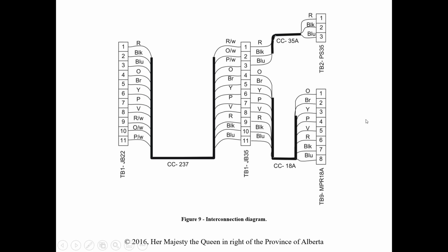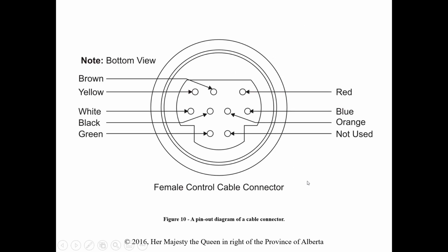Last one they talk about is the interconnection diagram. They show specific connection details, so no attempt is made to provide an indication of the function or location of components. It's literally, red goes to 8, or black goes to terminal 2. You could literally have no idea what these are doing, but still be able to connect this correctly. That's what an interconnection diagram is going to do.